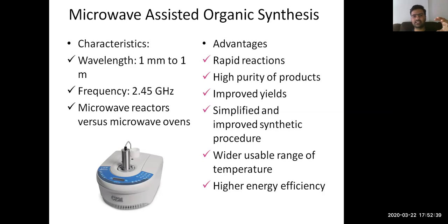So what it just does is, if at all you keep full power at 800 watts, then it will pulsate the microwave radiations. If for 1 minute you're keeping the microwave on, for about 50 seconds, it will keep the microwave radiations on. Okay, that would give an average power of 800 watts. Right? But it's not a uniform constant power being supplied.